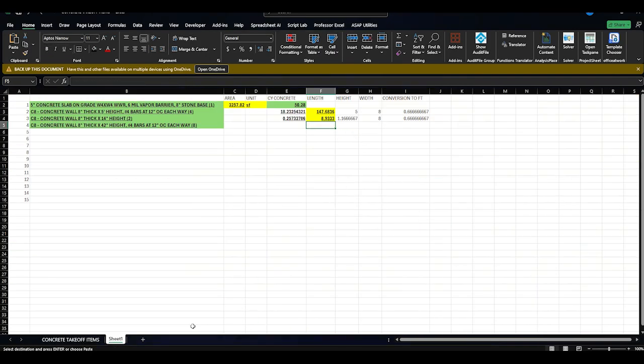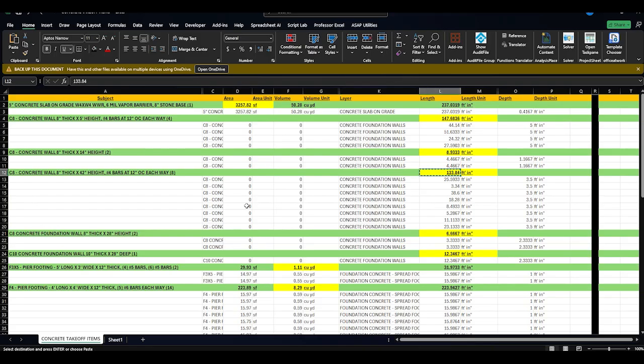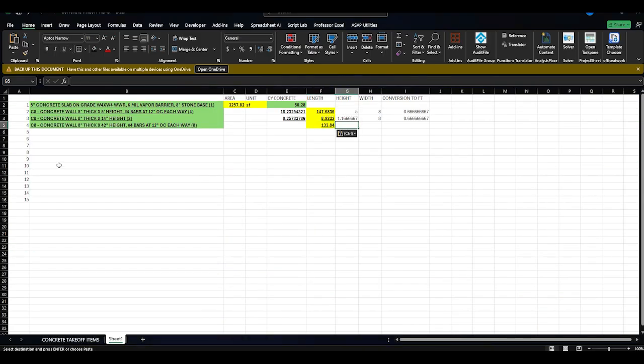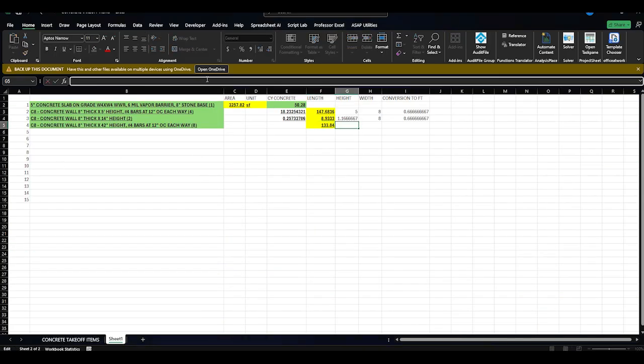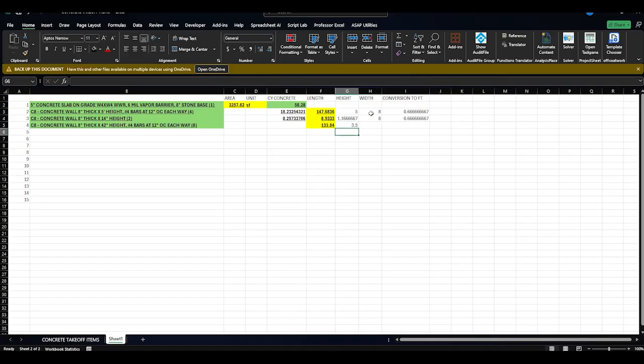As you can see, I'm continuing to go item by item down the list, copy and pasting from our original sheet, and then inputting the takeoff data measurements, and assessing how to convert that item into the unit I want to apply a dollar figure unit cost to. In most cases, that metric is cubic yards of concrete in this particular example.